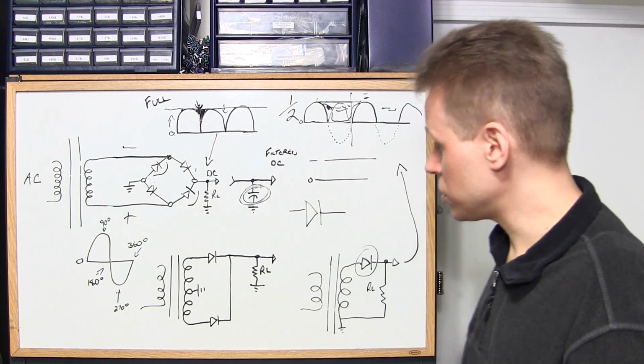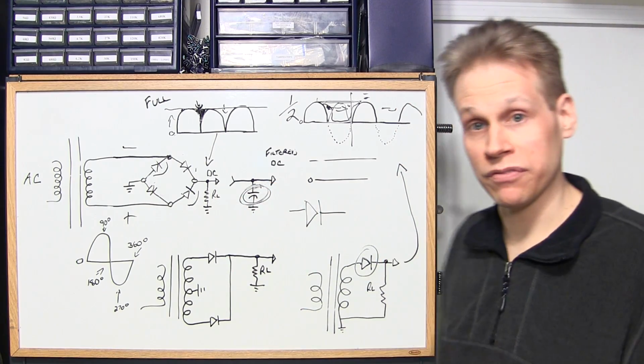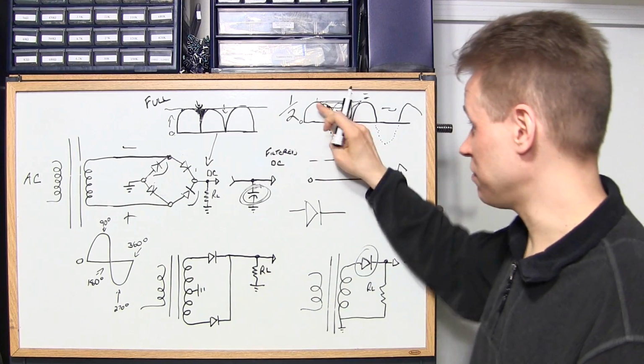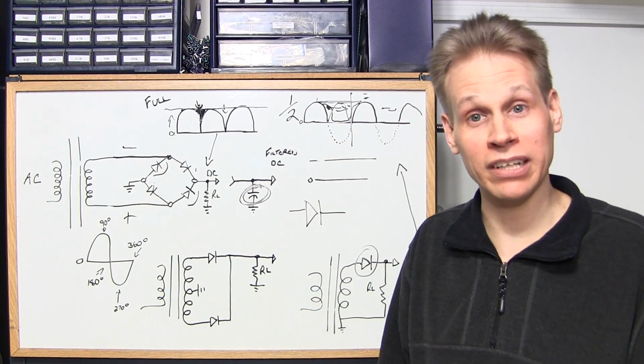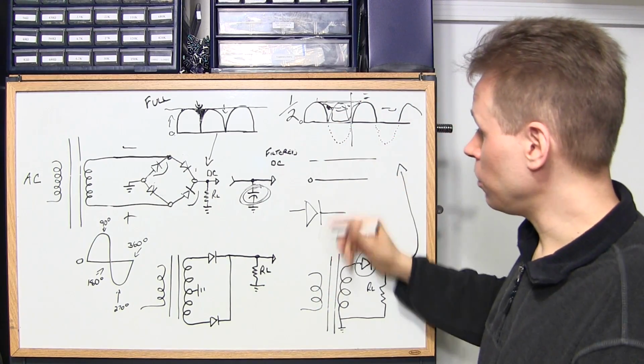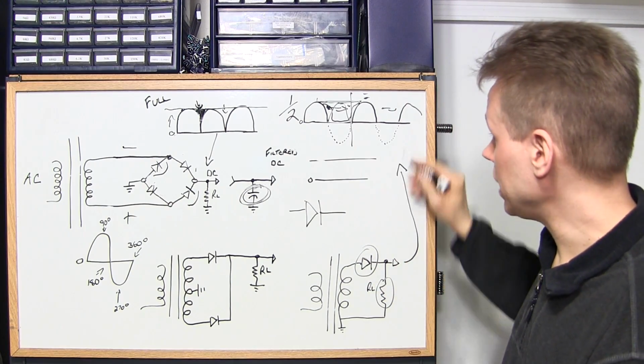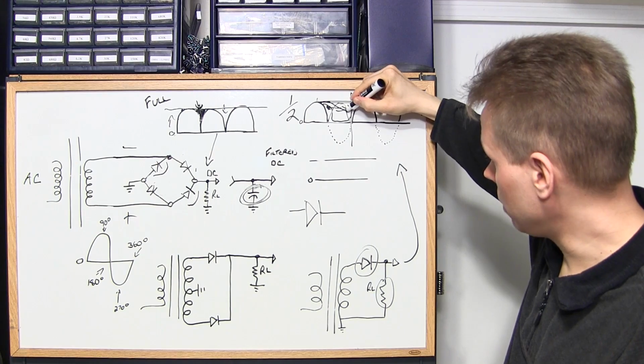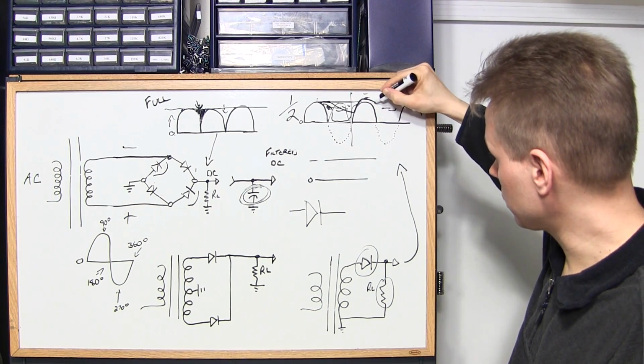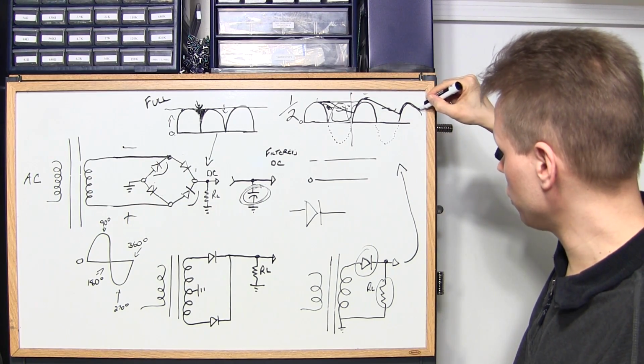And that's what a capacitor does. The capacitor is just acting as a filter, and they call it a filter, but really what it's doing is filling in the potholes in the road there. And again, if you start to pull really heavy load at this point right here, it's going to want to pull it down until it gets to the charge cycle again.